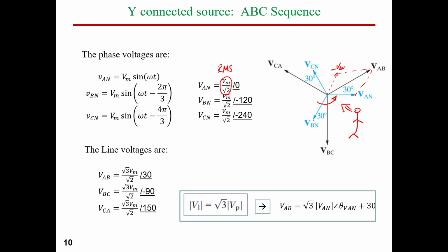So this is called the sequence. How the sequence is changing, guys, we will learn when we discuss the synchronous generator topics. The sequence can be changed from the supply or generator by reversing the motion of the shaft of the generator. It would provide negative sequence. So this is called positive sequence. Positive sequence is ABC. Negative sequence is ACB. Okay.